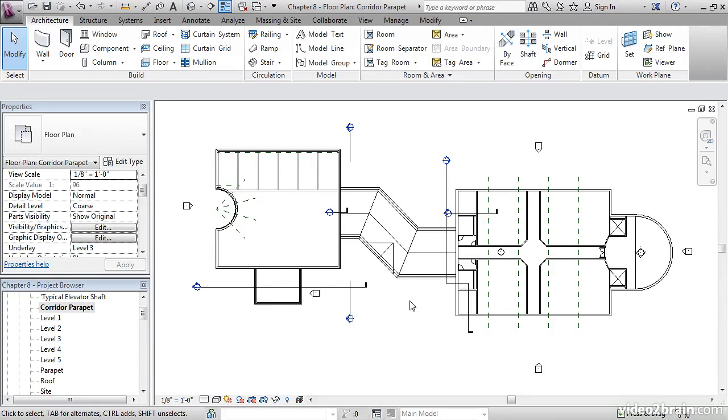I truly believe that Revit has enough tools that you can find the right ones and combine them to force the program to behave. By modifying the footprint of the roof, we were able to break the roof and add the slope arrows we needed to force a pitch along the eaves of the roof.